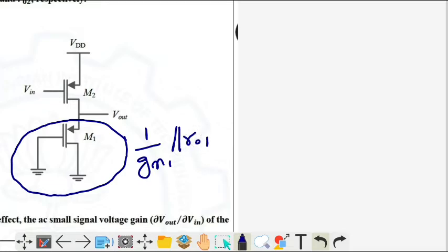And if it is given in terms of a p-type MOSFET, it is better to convert it into an n-type MOSFET, since the voltage gain for both MOSFETs, whether p-type or n-type, is almost the same. So let's do that. Since it is a DC source, for calculation of the voltage gain, it should be grounded. Once you do that and simplify, let's convert it into the n-type MOSFET.